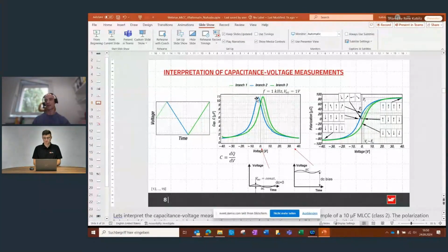The capacitance curve may have shifted, and what you see then, even at zero or low voltages, depending on which graph you are on, is a different capacitance. So in that sense, it could be important. If you operate your device nearly at full range or half, I mean, you should never design in at the full rated voltage.